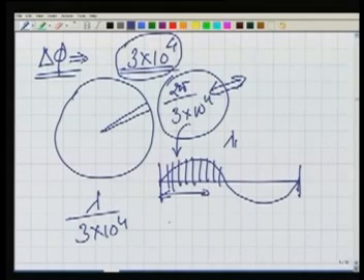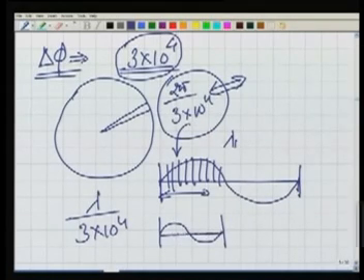Now, I can have another lambda which is smaller. This is again another important concept here, lambda 2. You can guess very well in which case, lambda 1 which is large or lambda 2 which is small, the least count of distance measurement because of the phase difference measurement will be finer.